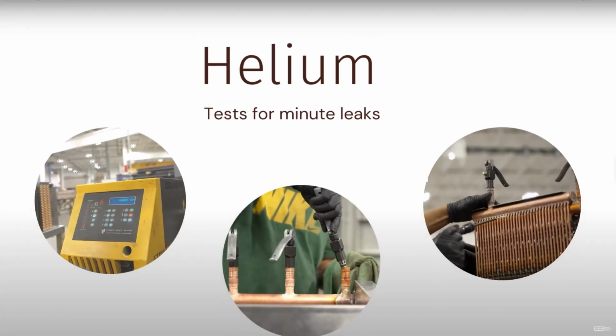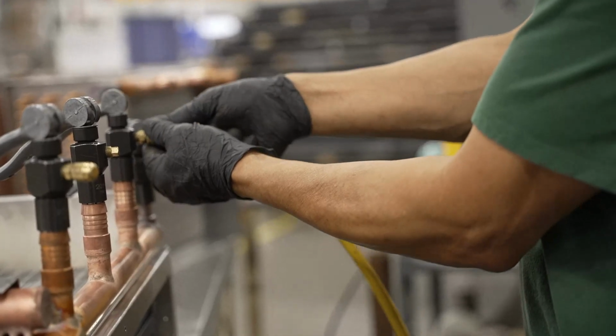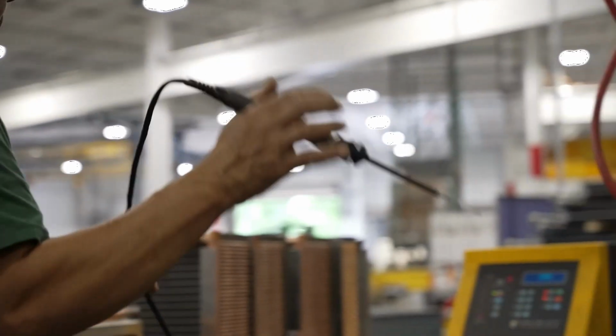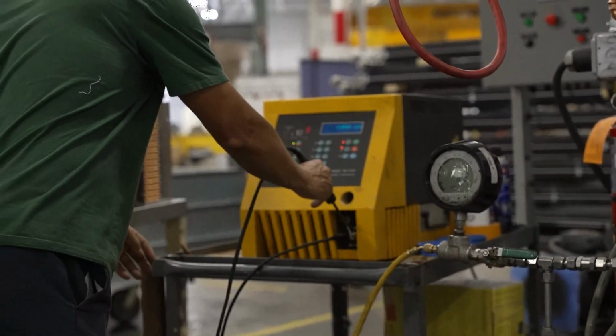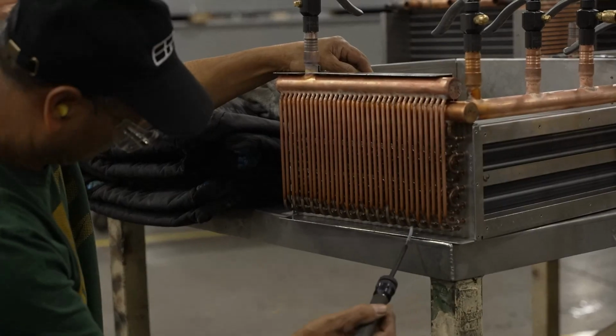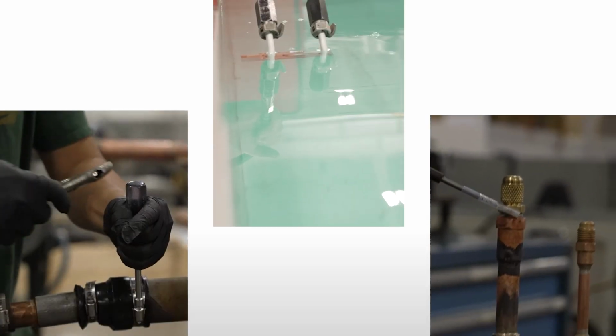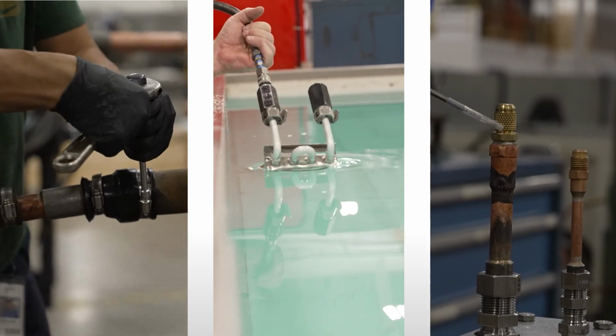The third method is helium testing, which is used to test for minute leaks. First, we fill the coil with helium and use a specialized mass spectrometer, often called a sniffer, to detect any trace helium leaking from the coil, pinpointing even the smallest leaks. All SRC coils are tested using one of these techniques.